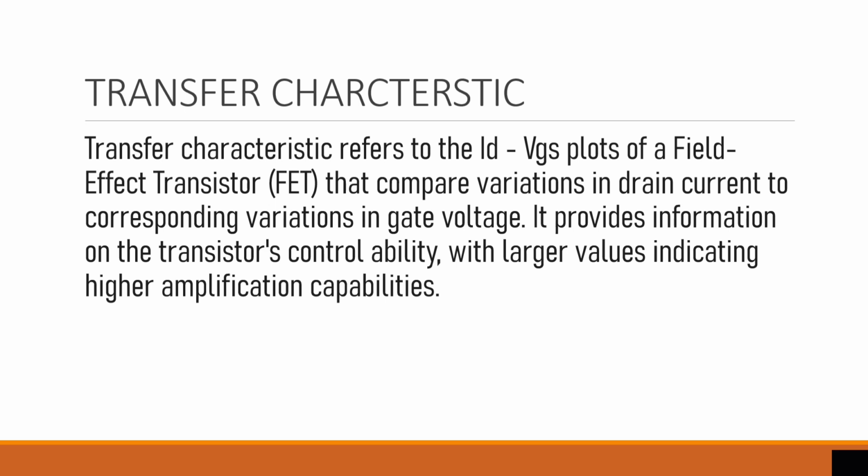Now we are going to discuss the transfer characteristic. Transfer characteristic refers to the ID-VGS plots of a field effect transistor that compare variations in drain current with corresponding variations in gate voltage. It provides information on the transistor's control ability, with larger values indicating higher amplification capability.